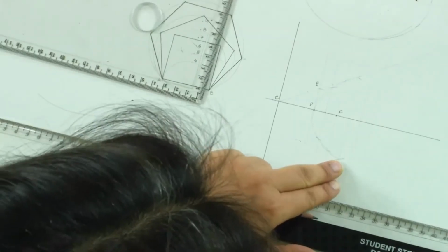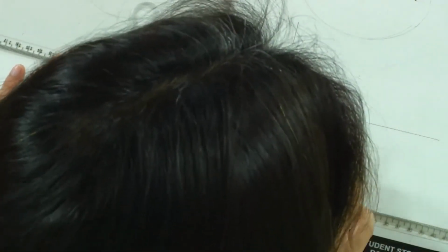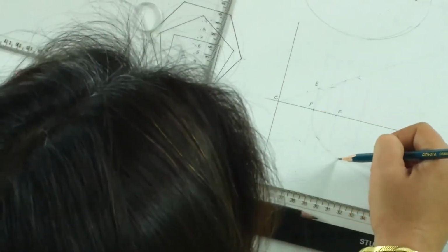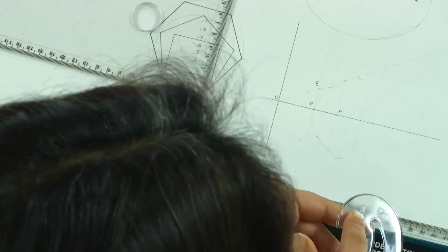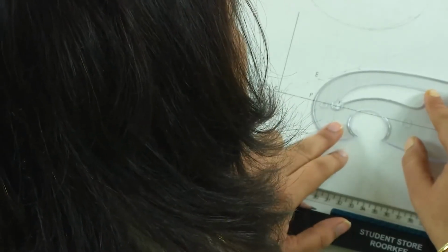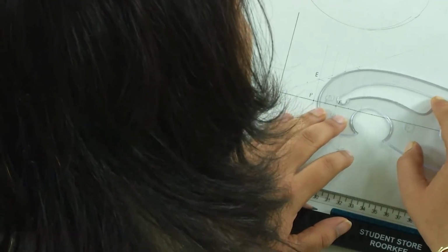But how do I fix it? You can draw a complete ellipse using the same method. However, I am only showing you how to fix the curves. For this, what we'll need here is a French curve. I'd already shown you the French curves. If you notice keenly, there is a number written on each of these curves. So what we need to do is fix the curve in such a manner that it passes through any 3 given points. And then we can keep fixing the curves such that the 3 points are being matched.